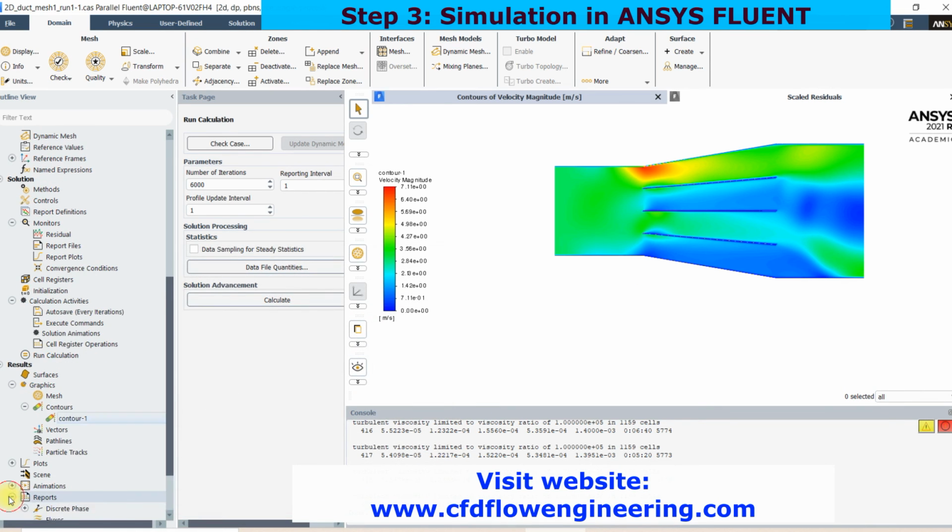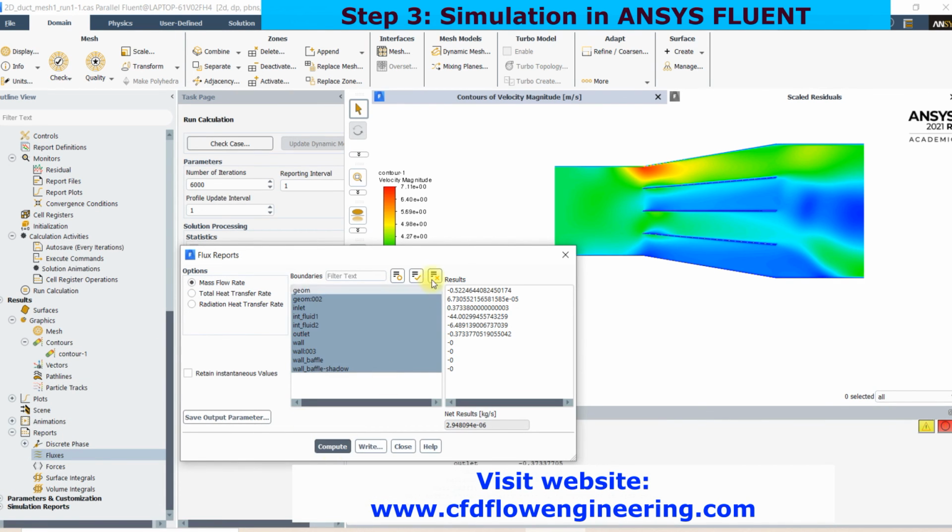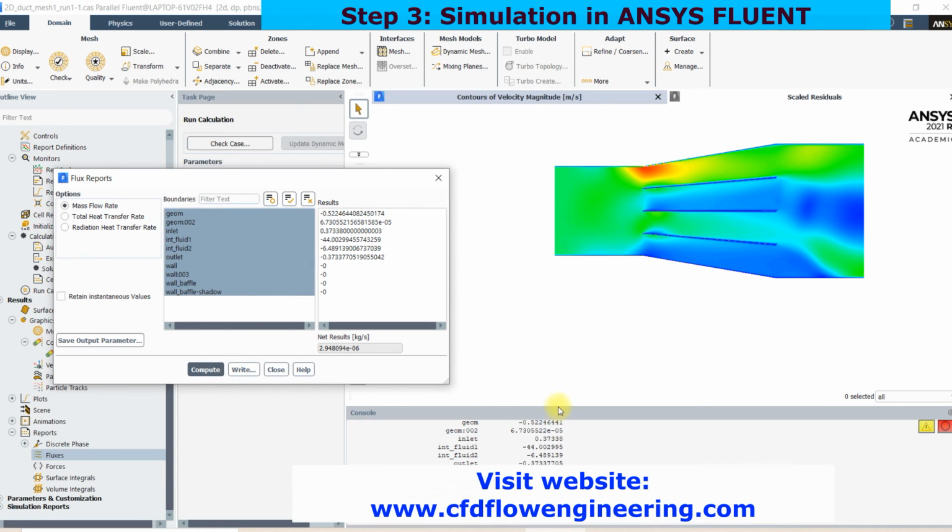Also check the flux balance. See, this is the flux balance. The net mass balance is around 10 to the power minus 6. That means it is close to 0. That means fluxes are well converged, the fluxes between inlet and outlet.